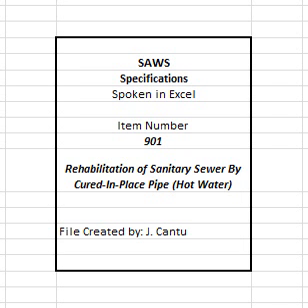A written log shall be kept noting the pulling force and any fluctuations in the pulling force. The force shall not exceed the manufacturer's recommendations. Any occurrences exceeding the manufacturer's recommendations will be cause for rejection of work.